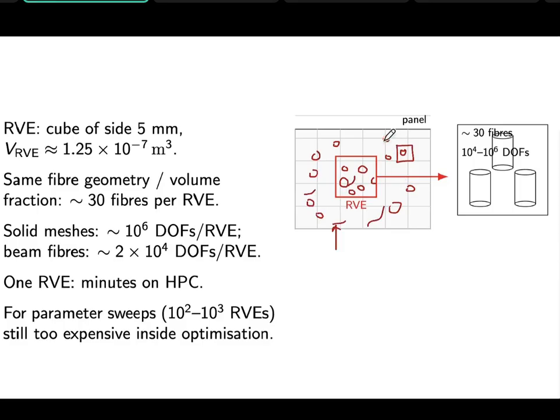You can also enlarge it and maybe take that into account. Okay, well, in that case, statistically, you will miss something because you do not have these nice little interfaces or cracks that are initiating. So such an RVE here has, let's say, a proper size because it's neither too small, meaning it does not include enough statistically relevant features, but it's also not too big because if you include all of that, well, then you include everything, yes, but you're very expensive because you have much more unknowns to take